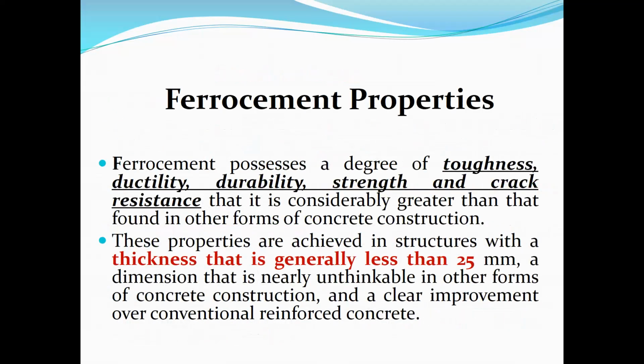Properties. They claim that it has toughness, ductility, durability, strength, and crack resistance that is considerably greater than that found in other forms of concrete construction. So a one-to-one comparison with concrete cannot be made, but in some places you will find these properties. And these properties are achieved in structures with a thickness that is generally less than 25 mm. Normal concrete cannot make a structure of 25 mm. So the toughness, ductility, durability, strength, and crack resistance are comparable. Okay.